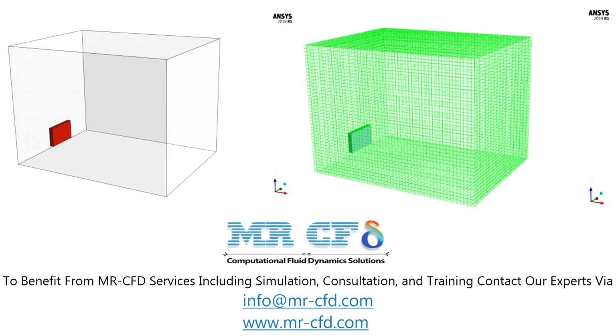We carry out the present three-dimensional model using Design Modeler software. The present model consists of a room in the shape of a rectangular cube with dimensions of 4 by 3 by 3 meters and a heater in the shape of a rectangular cube with the dimensions of 0.1 meter by 0.8 meter by 0.5 meter in its interior, which is connected to one of the room's side walls. And also the meshing of the room and the heater is done using ANSYS Meshing software, and the mesh type is also structured.